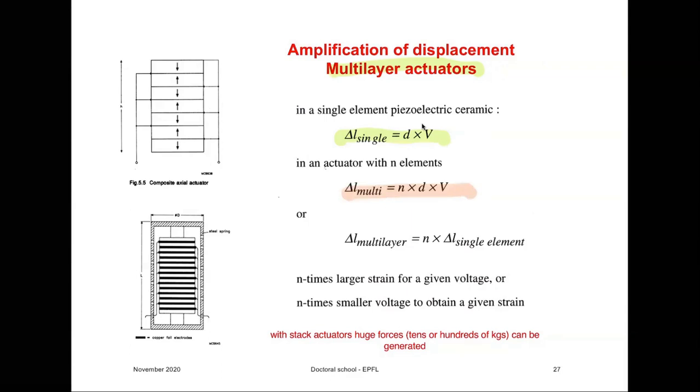How do you make this? Well, there are several ways in which this can be done. First, how connections are made. Usually you make connections this way. You would put piezoelectric elements that are poled like this and then stack them. And this can be done either by tape-casted layers or by just piezoelectric stacks of individual piezoelectric discs.